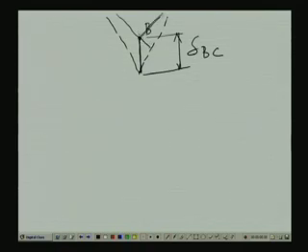Basically it should move in an arc, which is in a circular form. Since the deformation is small, we are taking this as a straight one. So, if we drop a perpendicular here, this is the deformation undergone by the inclined member, and if we call this deformation delta BD, this angle is 60 degrees in its original form.